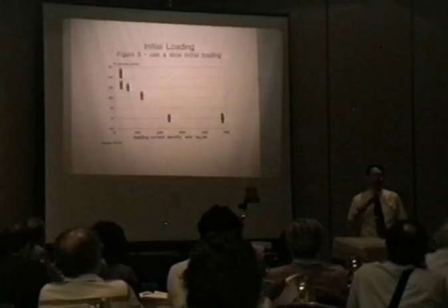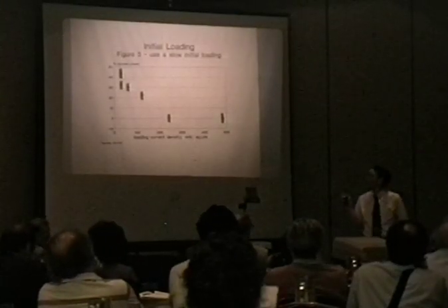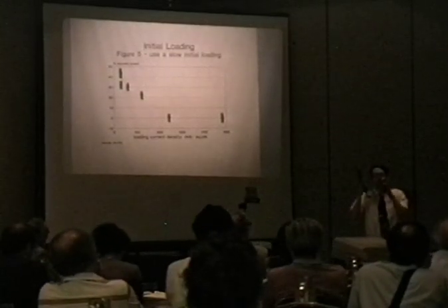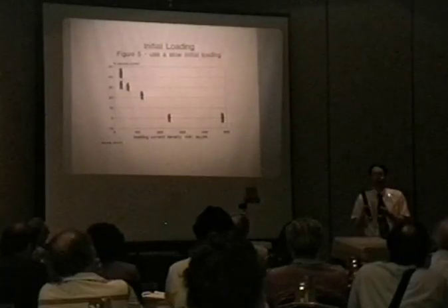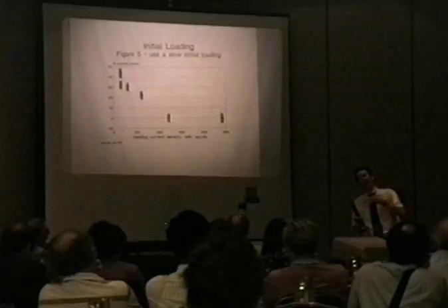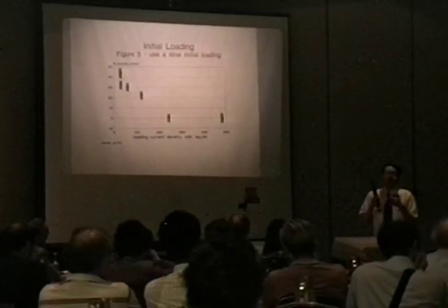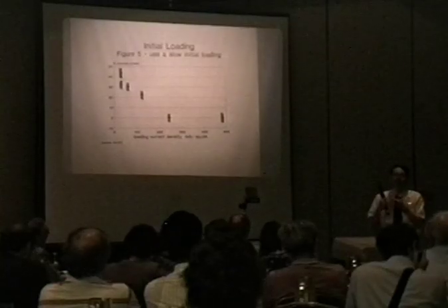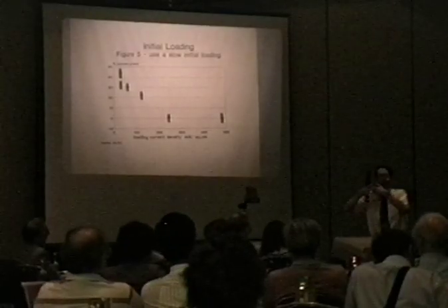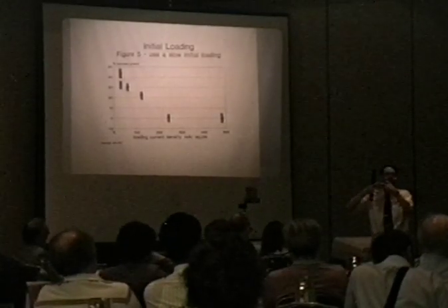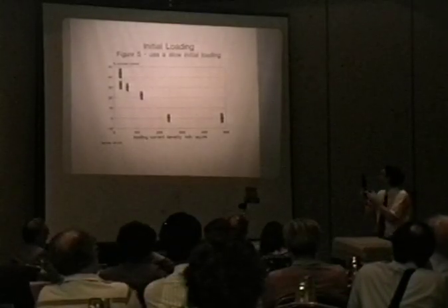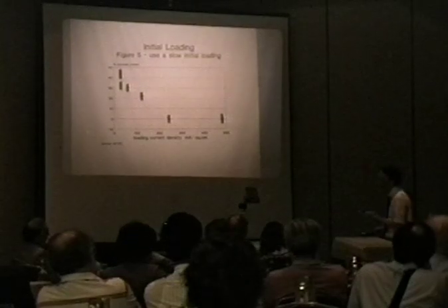Also, back on the roughness, one point I should have mentioned is that your bulk loading is dependent on where it outgasses, because the net loading is how much you go in compared to how much is coming out. And that is limited by that region that's outgassing the most. So when you have a rough surface, you have areas where your overpotential is less than at the peak. So if you have valleys, you have less overpotential, and therefore that will be some of the limiting sites of your loading. At least that's what I believe.